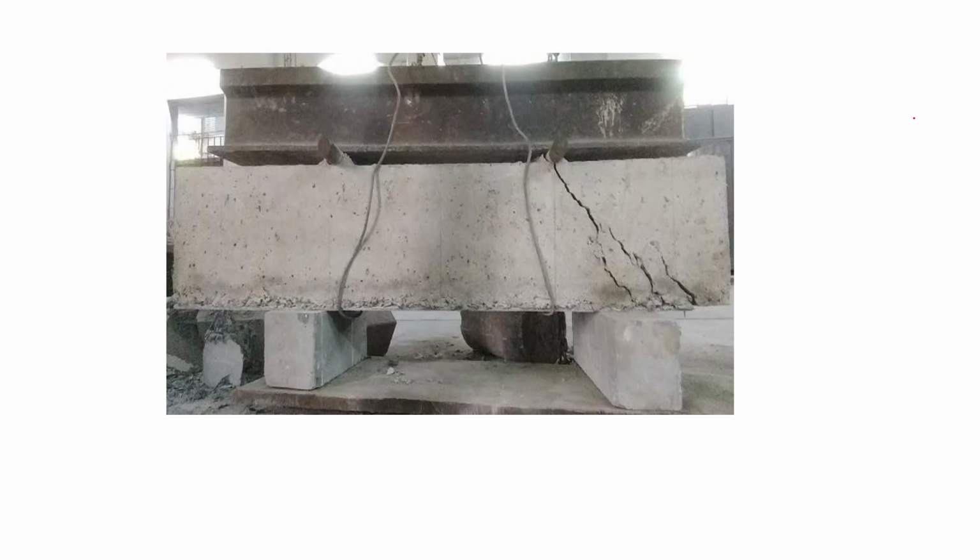Look at this beam which is loaded, and these are the shear cracks. You can see the shear cracks over the support, and if you look clearly, they aren't breaking straight up and down. The cracks are not straight, but inclined. You can see here, and the angle is almost 45 degrees.